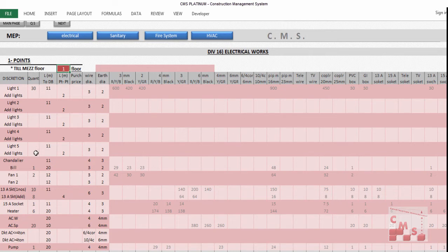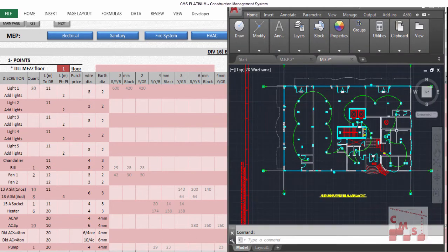The same you will do for a bell, for a fan, for chandeliers. Whatever you have on the ceiling, you will add it like this. So you will put the length between the main light and the dB, then the length between each additional light and the other, like what we saw now. So that's the main length, then the length between each light and the others, and this can be an average length, not required to calculate it one by one.